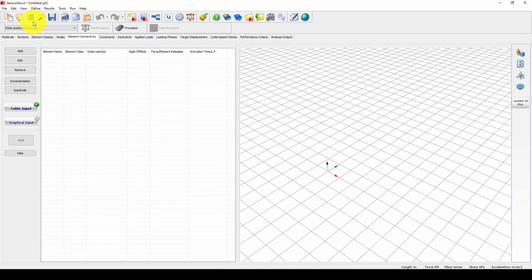So the first setting is, now you can change the story height as you wish. But in the previous tutorial we had the same properties. Okay, we create it. When I create it, I will enter the modeler, and I can model that. So I have already the AutoCAD plan on my desktop, and I'm going to here. So the same. If I create the existing structure, the column was 40 by 40, and the beam was 40 by 50, and the slab and infill panel walls, everything.